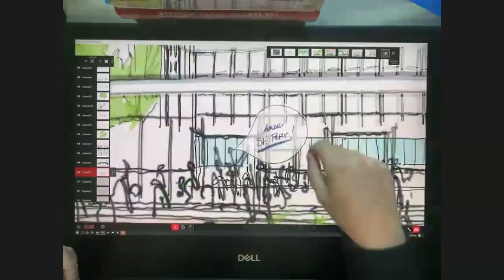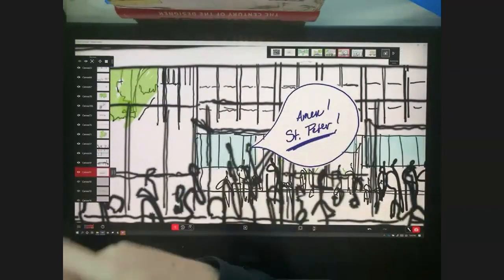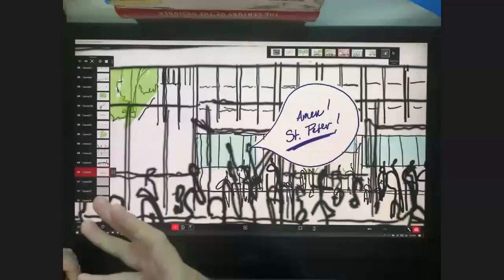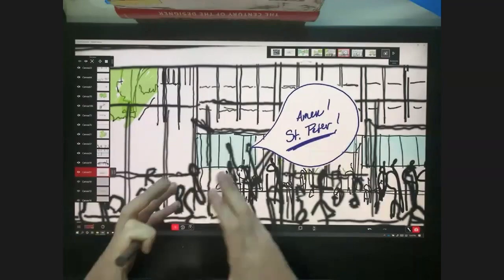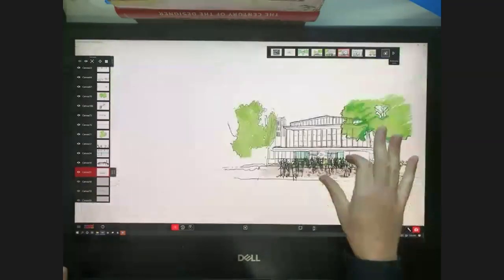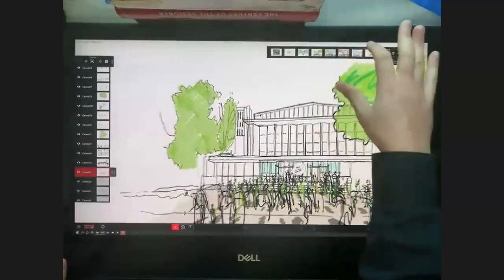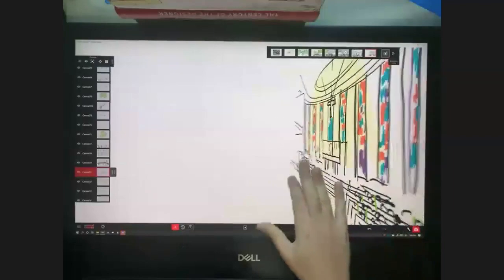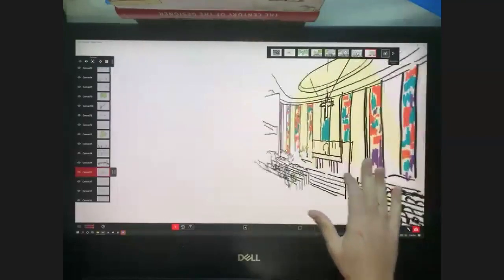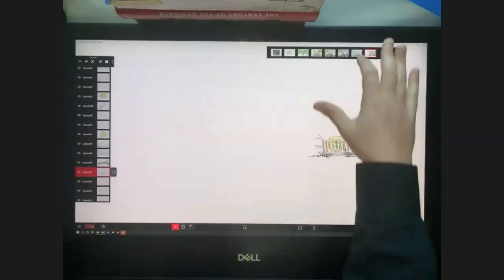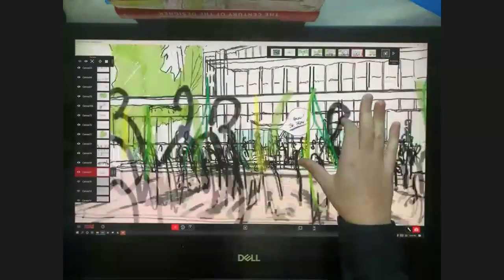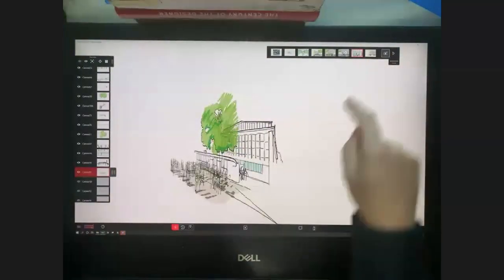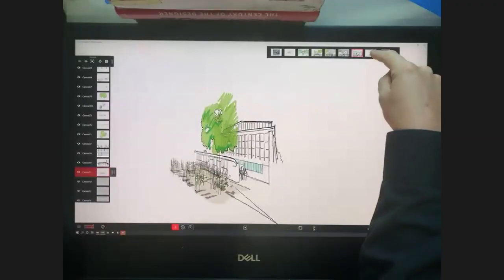And then in the bookmark tool, you can turn layers on and off to show up at certain scenes, so you don't see all the detail from a distance. From a distance, I wanted to reveal things, and then moving through to the inside to a very simple, just a 2D sketch. There's nothing more to that than a 2D drawing. But when you zoom out, if I turn all this on, and I have that sketch in this view, it's turned off. You don't see it until you get to the bookmark where it exists.